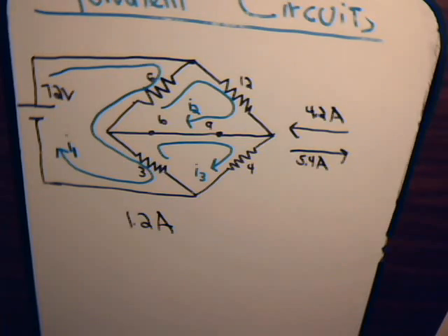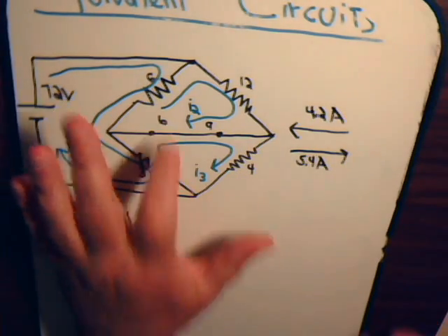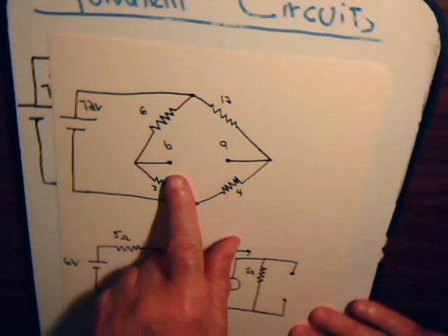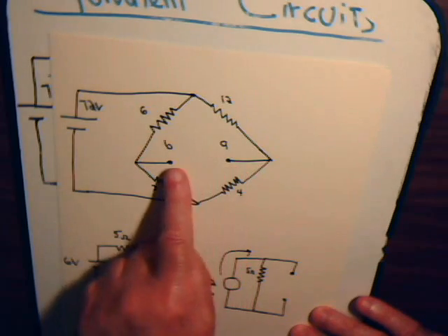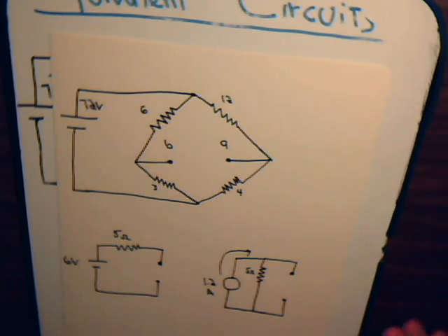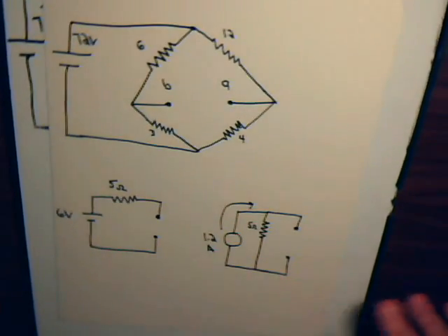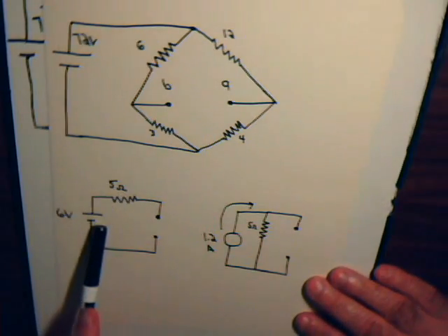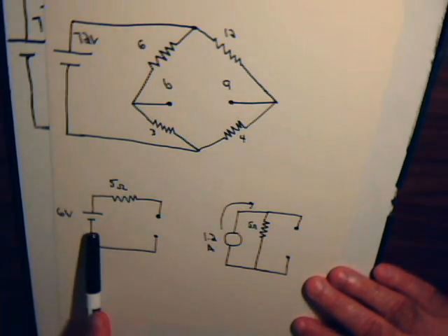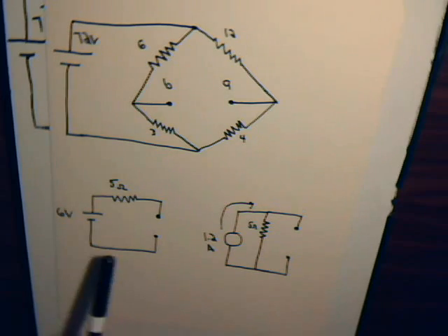So that, going back to our original circuit here, if we put an ammeter across here, the current it would measure would be 1.2 amps. That is the Norton equivalent current. And that's what we determined it to be before in the previous video. Only there, what we did was we first determined the Thevenin equivalent circuit, then used a simple source transformation, like you saw in video number 22, to get this answer of 1.2 amps.